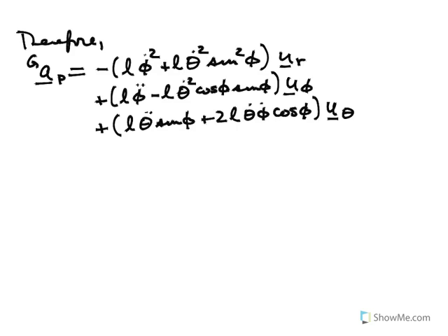So the key takeaway from this lecture is that if you use the rotations in such a way that when you describe the position, you express it in coordinates fixed in the last rotating frame, you have to apply the transport theorem from the last frame to the first frame, which requires you to compute the cumulative angular velocity, and then apply the transport theorem twice, once to get the velocity and then again to get the acceleration. And in the end, you're going to wind up with an expression in terms of the coordinates that are fixed in the last rotating frame, which is exactly what we have in both of these examples.